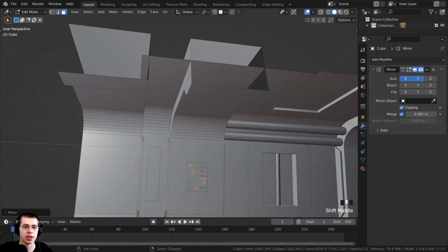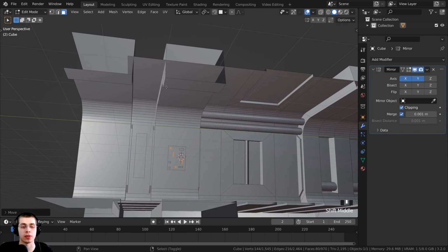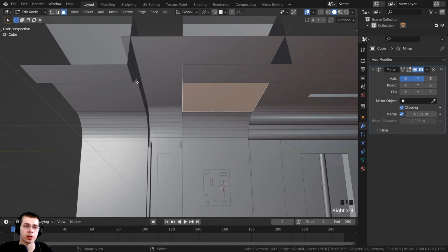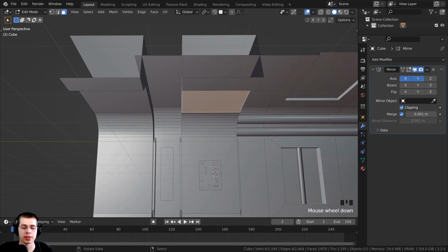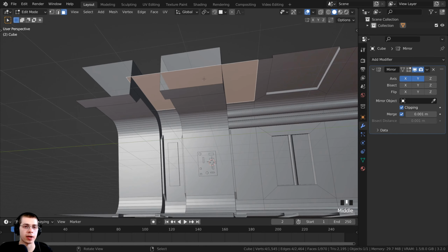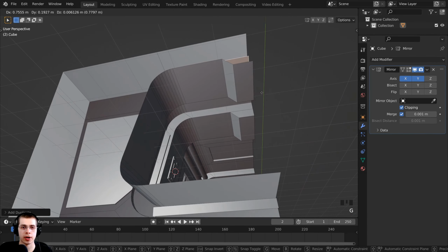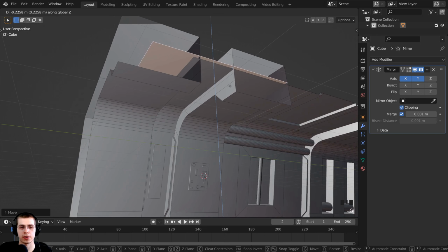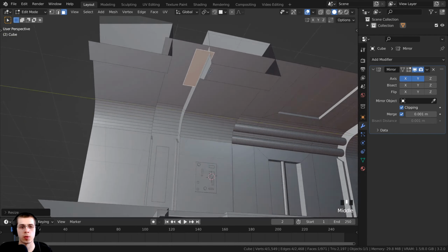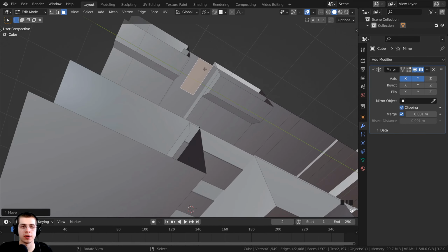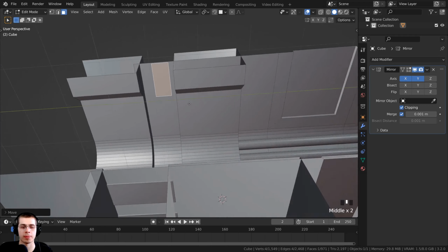Now also right up here, I want to add another light on the roof. And I want the light to be right there in the center of these two metal pieces. So to do this, I can just select this piece right here, and I can press Shift D to duplicate, and I can press G to grab. Let's also bring this down on the Z axis, and I can scale it down on the Y axis, and you can see because we have the clipping turned on, if I try to push it into the mirror, it's just going to stop there at the end.